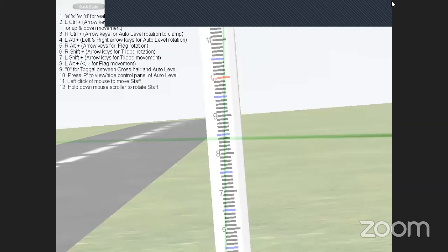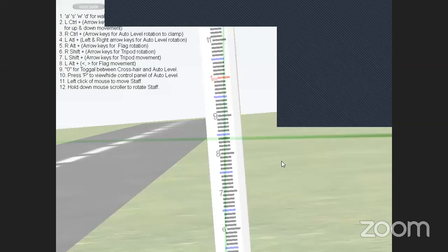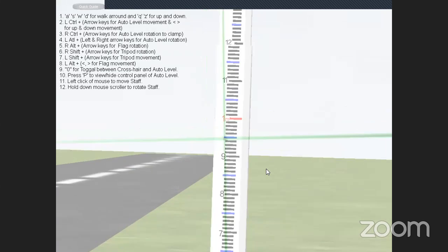First column is station, second column is back side, third column is intermediate side, fourth column is foreside. Then you follow any method, height of the instrument or rise and fall method. Then RL of the points, then remarks. This is the level book we say.